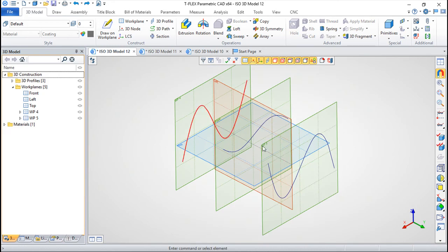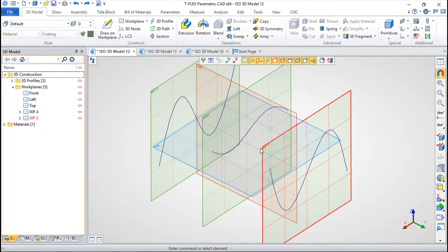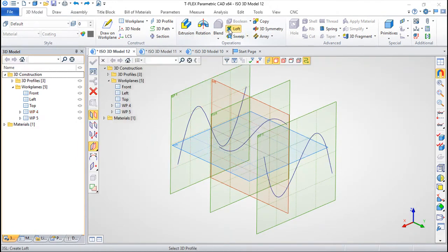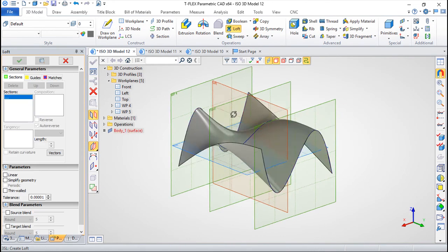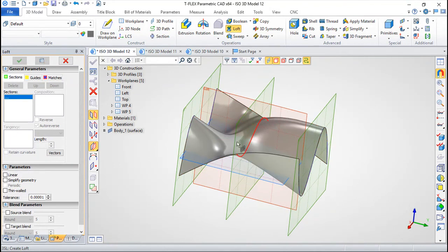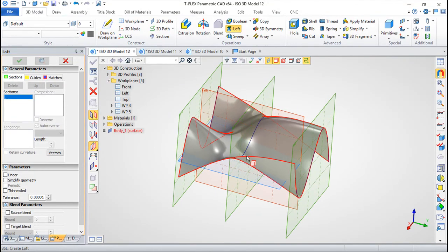Last example, I've created 3 work plans also. This time with splines. We have open profiles, not closed profiles. So the idea is exactly the same. So 1, 2, and 3. So I can do a lot of things around here. So if I say simply this, I get this very nice shape. But the principles are the same with the controls on the sections and working around all of these things. So the Loft command, these are the basic ideas to use the Loft commands.